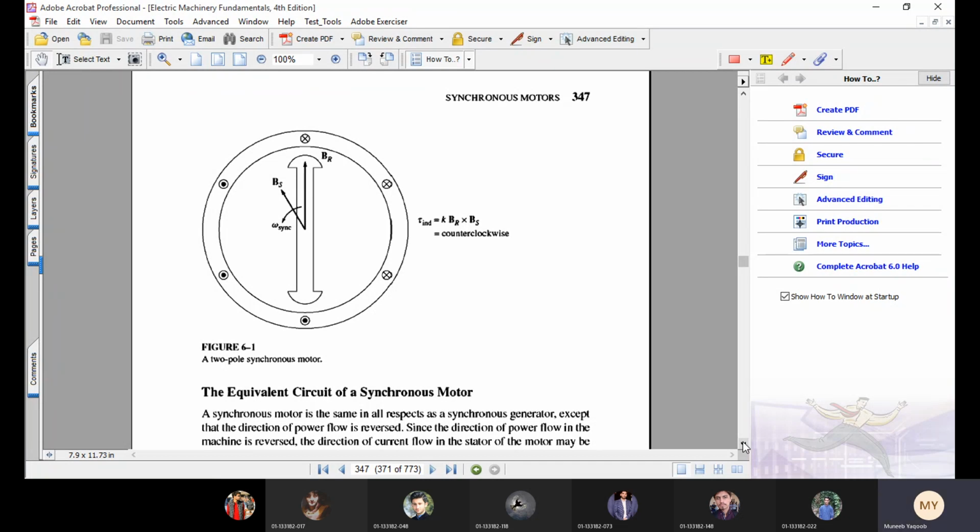So when we switch on the motor, this capacitor provides a phase difference between the current flowing in the motor winding and the current flowing through the capacitor. Due to these two phases, a phase difference is created, and now this single-phase machine starts rotating as a two-phase machine.